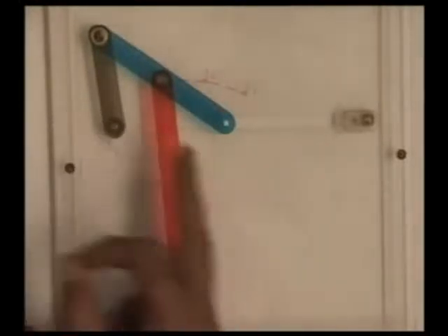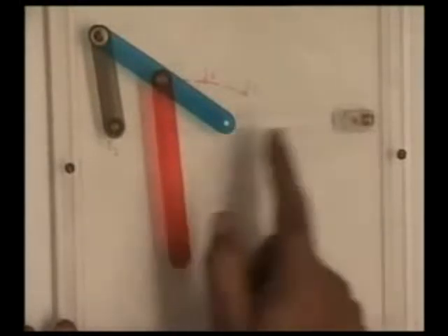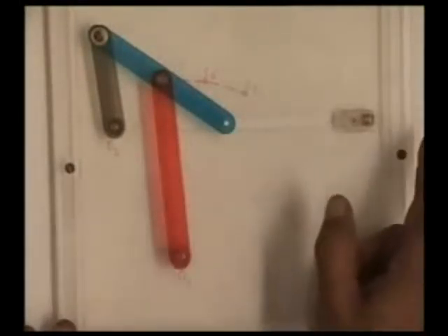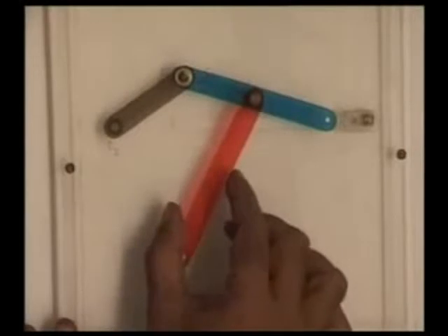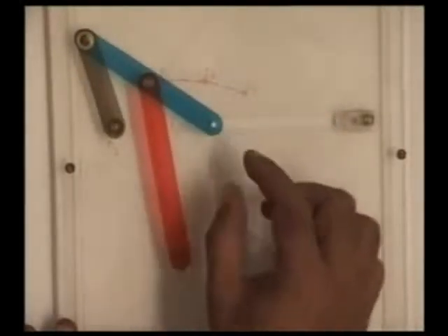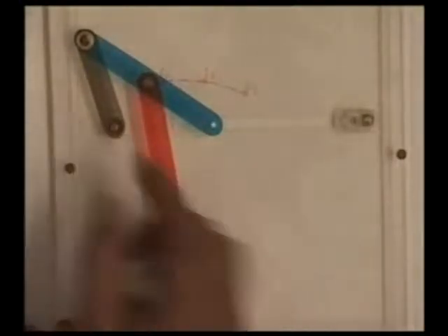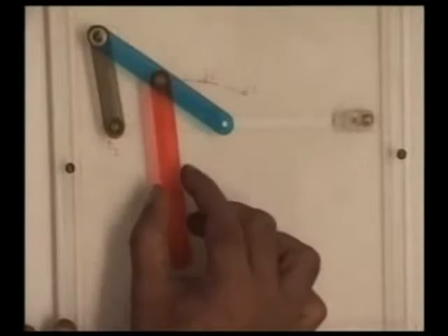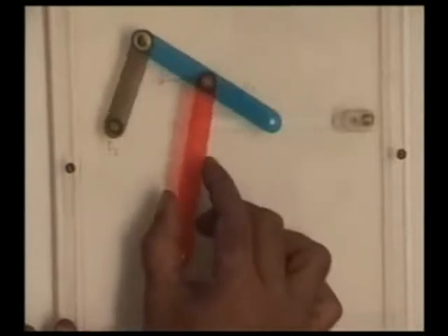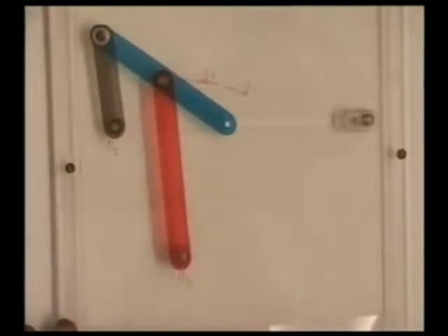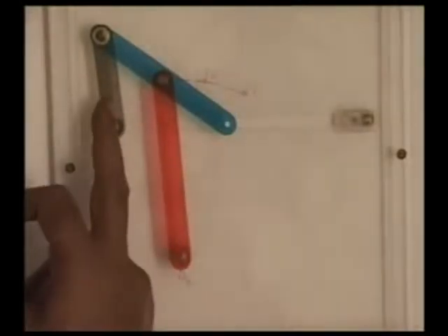Now if we move this linkage, what we should see is that this point of the coupler is still following the original straight line, but only approximately. We can notice that this coupler point, though not guided by the slider as before, the slider is totally detached, but this 4-bar linkage is also driving this coupler point through the axis of this slot where the previous slider was moving. So we have generated a coupler curve synthesis problem or path generation problem coordinated with the input movement.